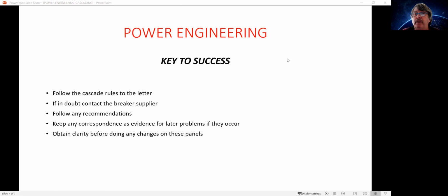Main thing, just in summary, if you are using a specific brand and you think that you will go into this cascade offering, sometimes you might be in the panel board supplier or manufacturing side. You might be able to spec something to be made to your requirements. Go back to that manufacturer, get the details of what is in their cascade offering, and get a very good understanding of what needs to be done to ensure that that cascading happens.